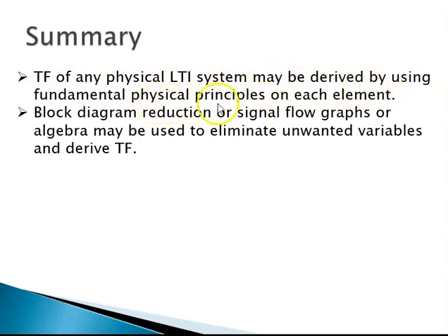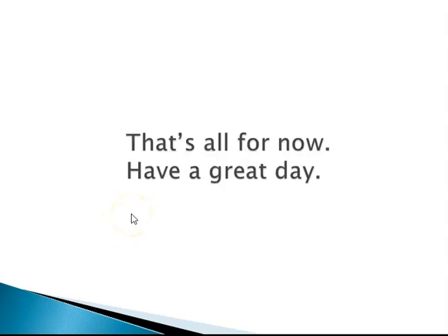In summary, we may say that the TF of any physical LTI system may be derived by using fundamental physical principles on each element. And once this is done, either using simple algebra or block diagram reduction or signal flow graphs, which we are going to see later, we eliminate unwanted variables and derive the transfer function.